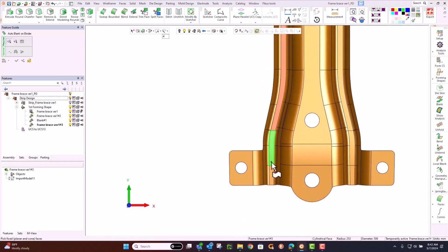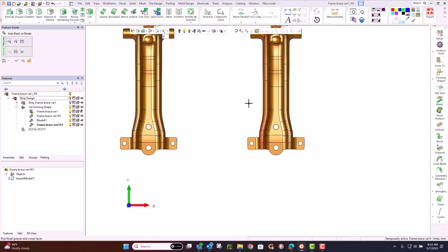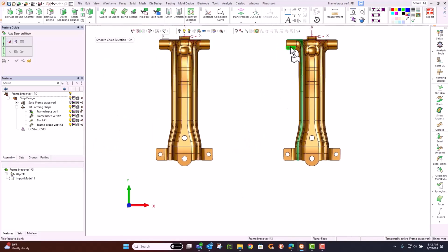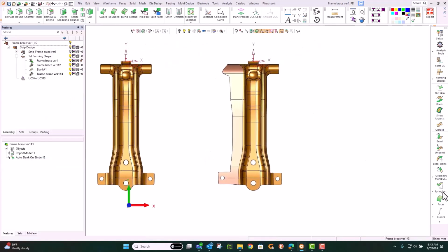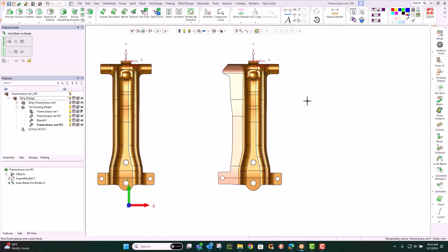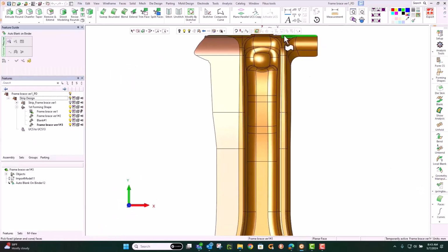So the system is smart enough to find those areas. It applies the material properties when it comes to the unfolding of that flange, and it'll keep the flange anchored to those faces that we picked initially, like you see here. So quickly it develops out in just a matter of a few seconds. Going further, we'll do the same to the opposite side, and we consider that one station where we're doing the unflanging on both sides.